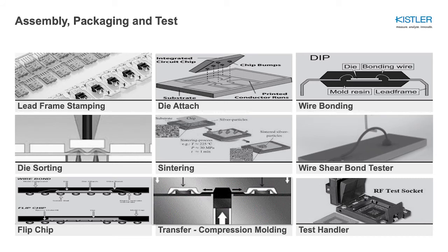Die sorting is the process of removing a die, package, or device from one carrier medium and placing it into another carrier. When you install a piezoelectric force sensor into the die ejector, you are able to monitor the amount of force which is applied during the removal process.